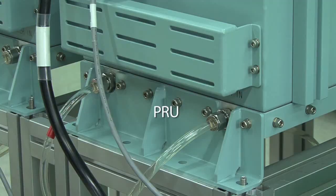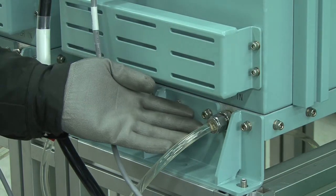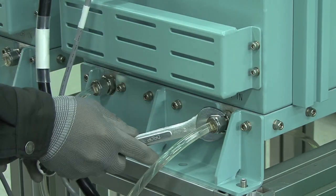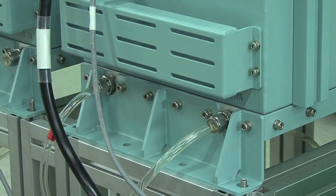Three. PRU. 3-1. Checking leakage of cooling water connector. Step 1. Check leakage from both inlet and outlet cooling water connector. Step 2. Tighten the connector using tools in case of leakage. Step 3. Reassemble the connector if the leakage continues.